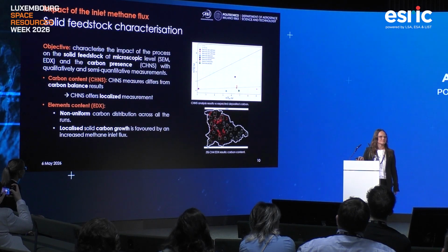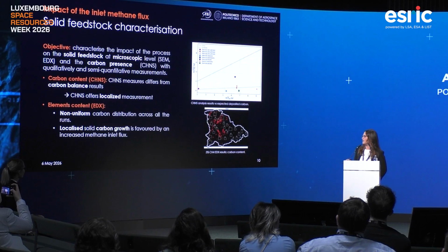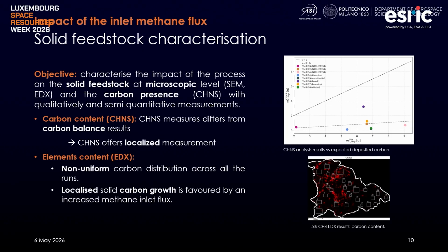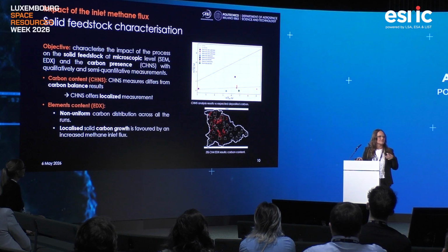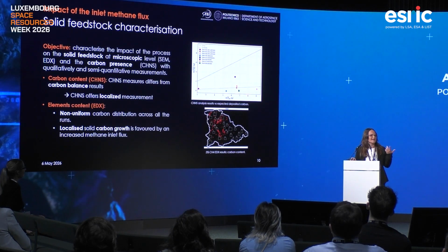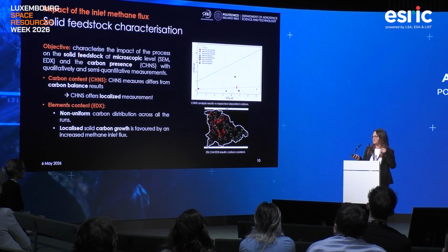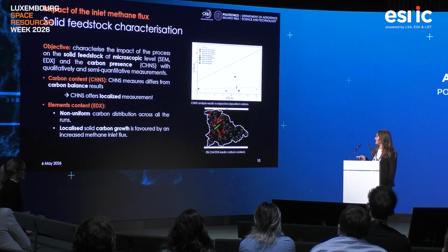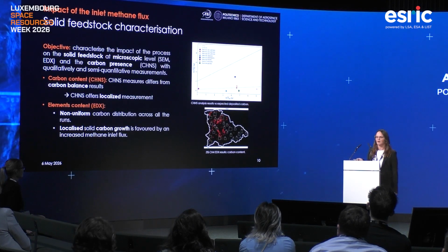So after the test, the different reduced material, our goal was to try to quantify this carbon content, because the values I've shown you before are computed theoretically from the CO, CO2, and methane evolution. So we tried to perform some CHNS analysis, but the results were very different from our theoretical values, meaning that those measurements were really localized and not relevant to test the total carbon evolution. While at the EDX, we found the carbon deposition in all the fragments.